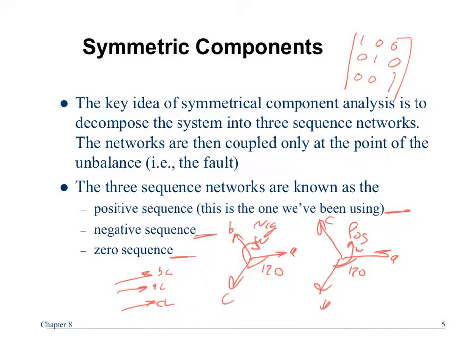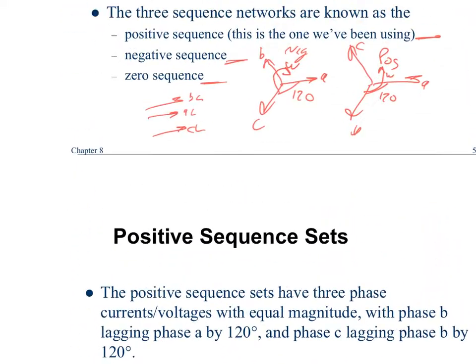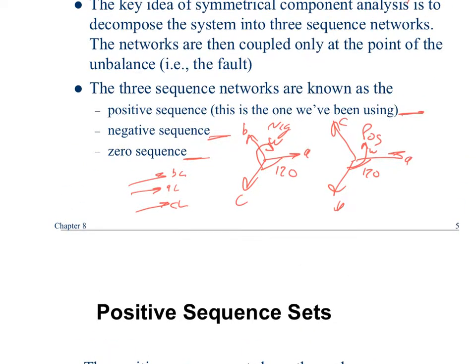That's why this is called symmetrical components, not balanced components, because the concept of a balance is same magnitude, phase shifted by 120 degrees. In zero sequence land, we don't have any 120 degree phase shift. And that will hopefully become evident when we start looking at ground. Is that single phase? No, it's all 3-phase systems.